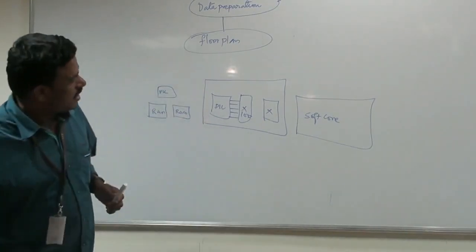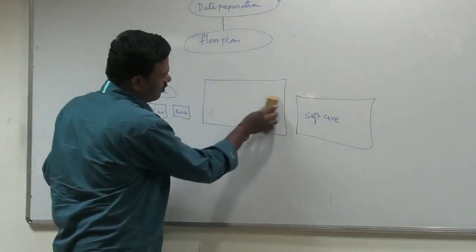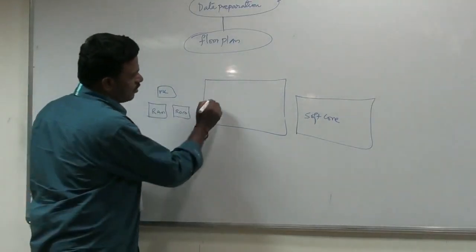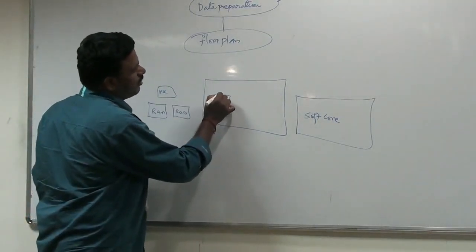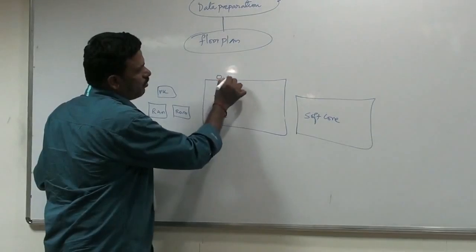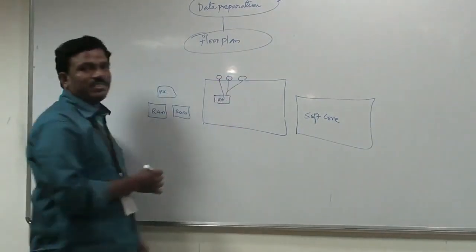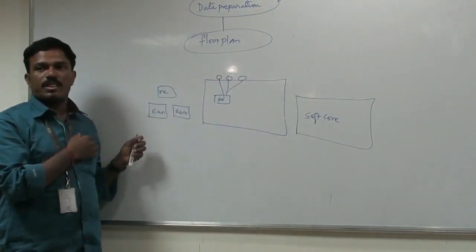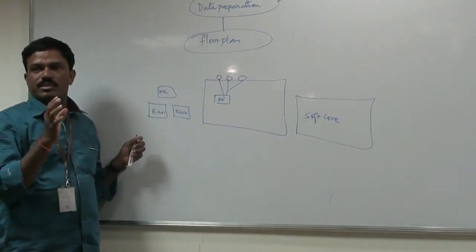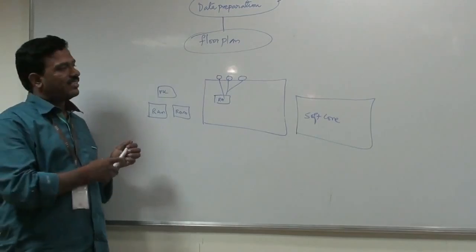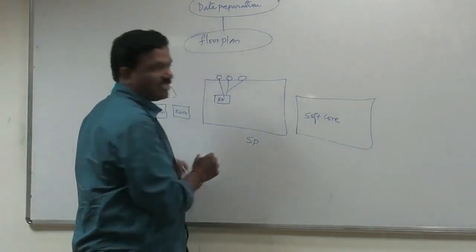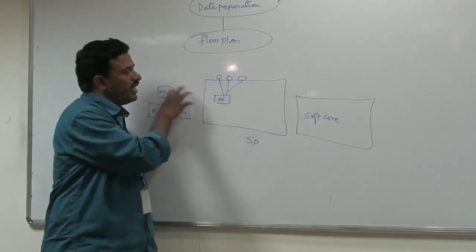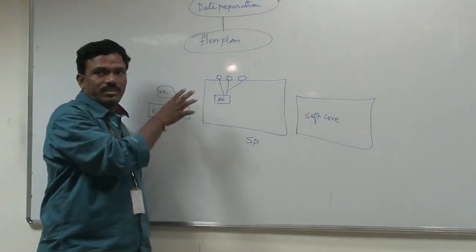Then in the floor plan, right, simply we should not place our analog as well as digital according to our wish, right? If suppose I have a RAM, so that RAM is having some IOs. So suppose I have IOs here, this IOs connects with this RAM. Then I need to keep this RAM very close to this IOs. Based upon the interconnects, which are represented with flylines, when you touch the block, the tool will give you the interconnects associated with the entire design.